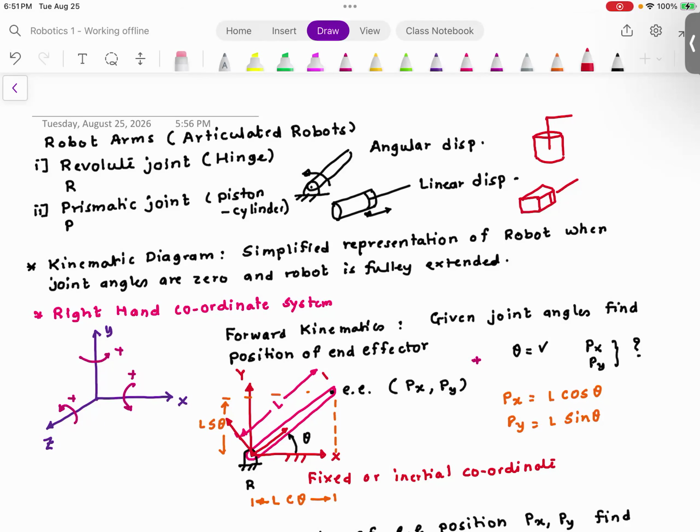We talked about different types of joints in the robot. You have the prismatic joint, which indicates translational motion, and there is the rotary joint or the revolute joint that indicates the rotary motion. Your robot may have complex joints. So for example, a robot would have a shoulder joint, but the shoulder joint is represented as two revolute joints which are perpendicular to each other.